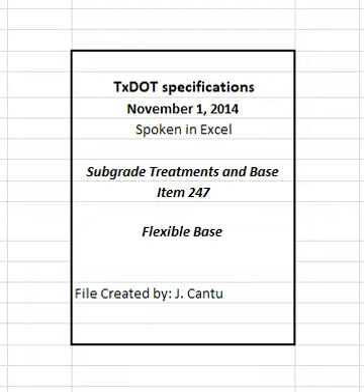3.1 Provide rollers in accordance with Item 210, rolling. Provide proof rollers in accordance with Item 216, proof rolling, when required. 3.2 When ride quality measurement is required, provide a high-speed or lightweight inertial profiler certified at the Texas A&M Transportation Institute. Provide equipment certification documentation. Display a current decal on the equipment indicating the certification expiration date.